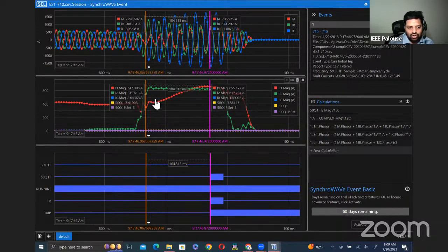So what kind of fault is this, where you don't have a zero sequence component and you have a negative sequence component that picked up very rapidly? It's nothing but a current imbalance fault. These components help us make decisions within the relays and when looking at the event records. I couldn't find other records, and some of these records are not available to the public, but there are many other faults that could also be represented in this fashion.